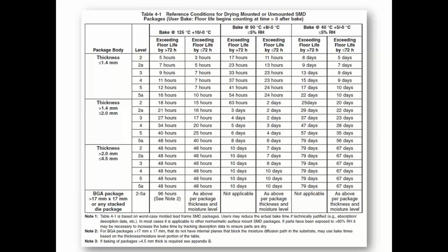We're not going to go through all of this chart, but I just wanted to have it there, and it's in the slides when you receive them. This is the sort of detail that you'll find within the standards, which give you, again, guidance on bake times, how long, what temperature for different packages and different thicknesses. So again, it's a useful source for deciding on what you're going to do with components that are susceptible to damage during soldering and rework and repair.